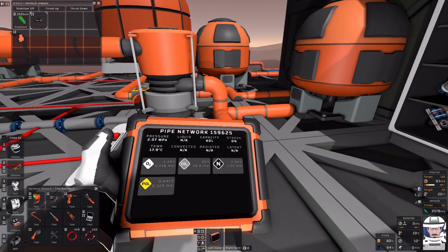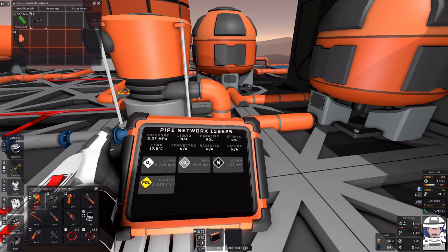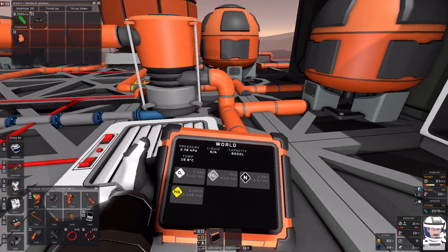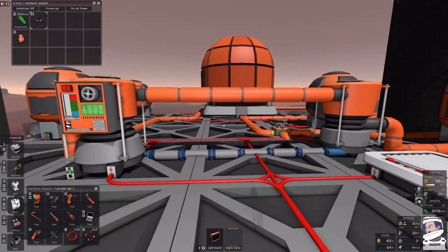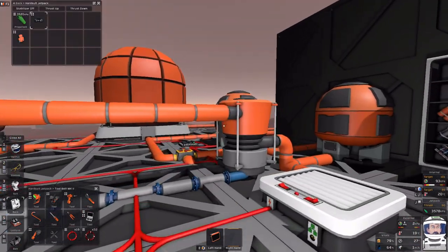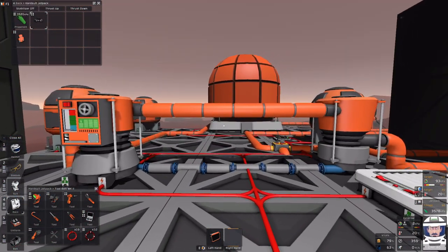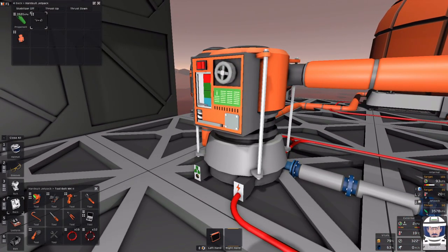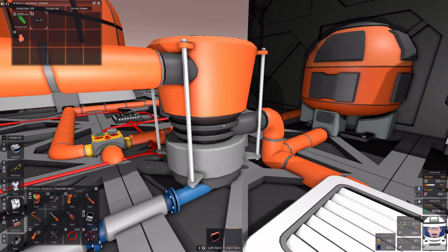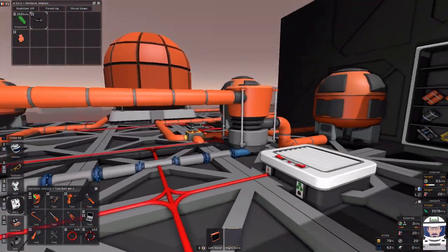So I just pressurized this to 2 megapascals. The more, the better. But I don't want to deal with phase change issues with the pollutants condensing. So with that, once again, evaporation chamber connected to my target, condensation chamber connected to my stable temperature source. This will be a cooling setup. On a heating setup, it will be the opposite. This will be a condensation chamber. This will be an evaporation chamber. And overall, no real change to the skeletal structure.